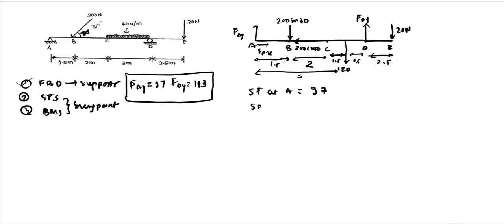And we also have a shear force just left of B. Whenever there is a sudden force, like at B where there is a force of 200 which is an inclined force, you need to calculate the shear force at left and at right of that point. Say at E and at D also there are such forces. They will suddenly jump values at that particular point, so you need to have an idea of how it is varying there. So it is suggested to calculate the shear force just left of B and just right of B whenever there is a sudden force at a particular point.